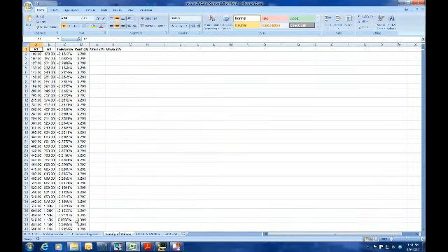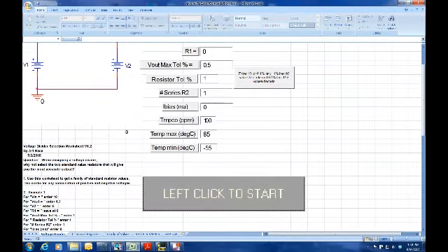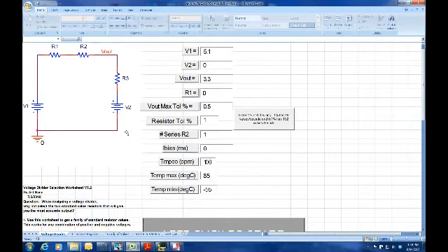So you can see that this program will provide you with a very fast means of calculating a voltage divider for any given situation. And we use voltage dividers a lot, especially in comparators and in power supplies. We're going to have a reference and a feedback voltage, and we need a divider to get the proper voltage so that the V out is equal to some V ref somewhere.